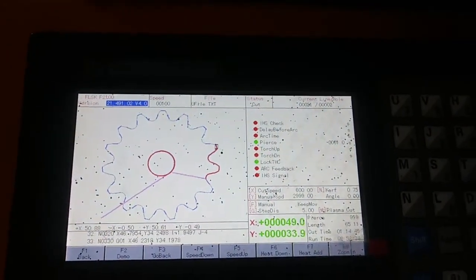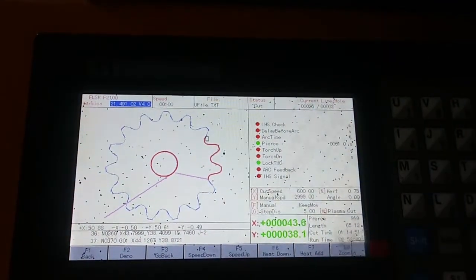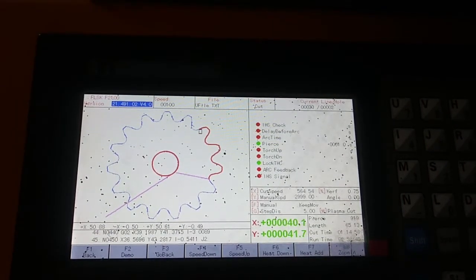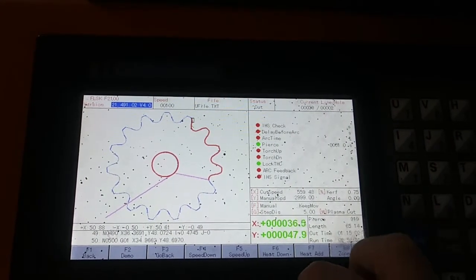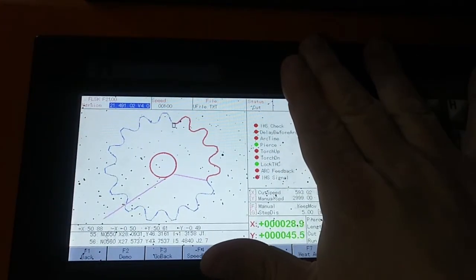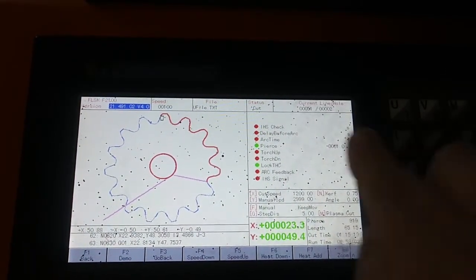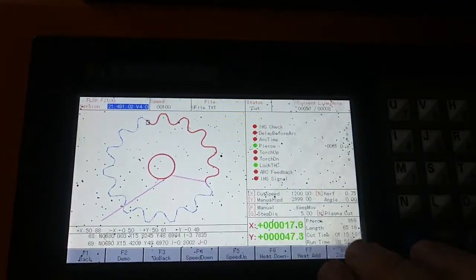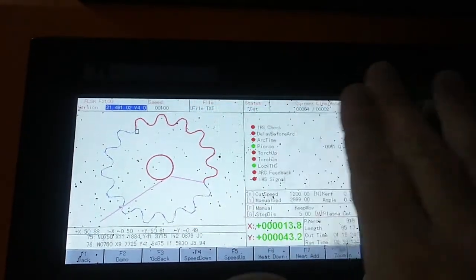And a way to tell also if your stuff is set up correctly is by hitting the F4 and F5 buttons, which speeds up the feed or lowers it. And if you click on that, which I'm doing right now, and it doesn't change the speed or feed, that means it's running straight from the G code and nothing else. So you don't have to worry about the machine hitting a wrong number, like an 8 or a 1 or whatever, and going out of control and the cut speed changing. So right now it's doing everything from SheetCam, or the G code rendered by SheetCam.